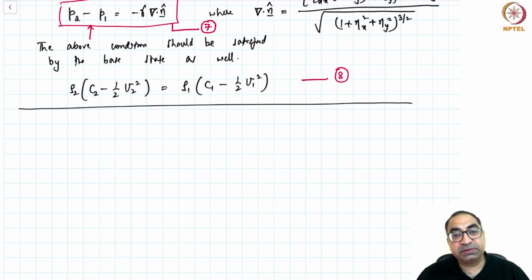Now when we perturb the interface, we also will have similar perturbations to the velocity field. Now the velocity field, recall, is represented in terms of a velocity potential. So we'll also perturb the velocity potential. If phi1 is the velocity potential of the lower fluid, this would be u1 times x. This is the base state. But now we introduce a perturbation to it, which is something like phi1 prime. And then we will do the same thing for phi2 as well.